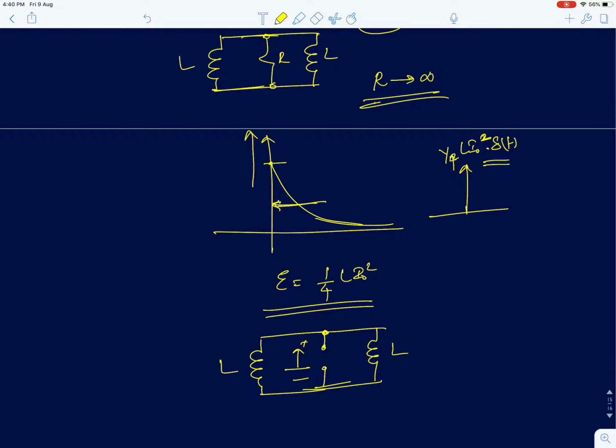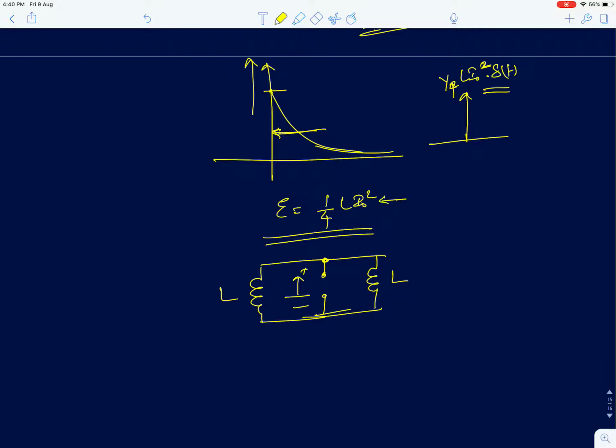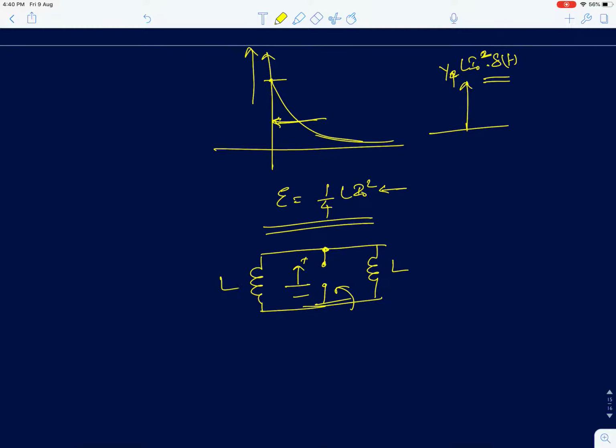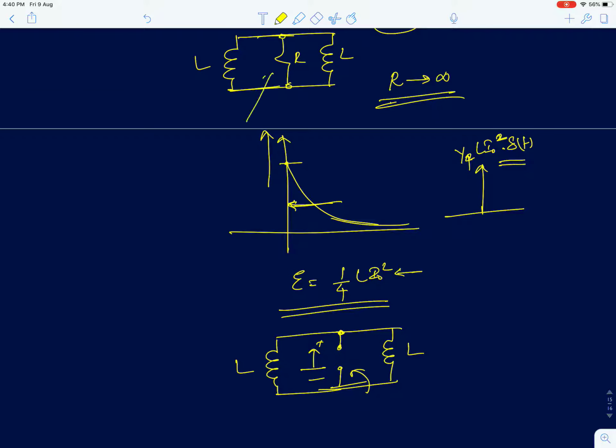The power becomes an impulse across the resistor, the open element. And there was a finite energy loss associated with that open circuit, and that value is 1/2 of the initial stored energy. So that's where the energy is actually lost. Since we have assumed a resistor, we could actually prove that the energy loss in the resistor is lost as heat.